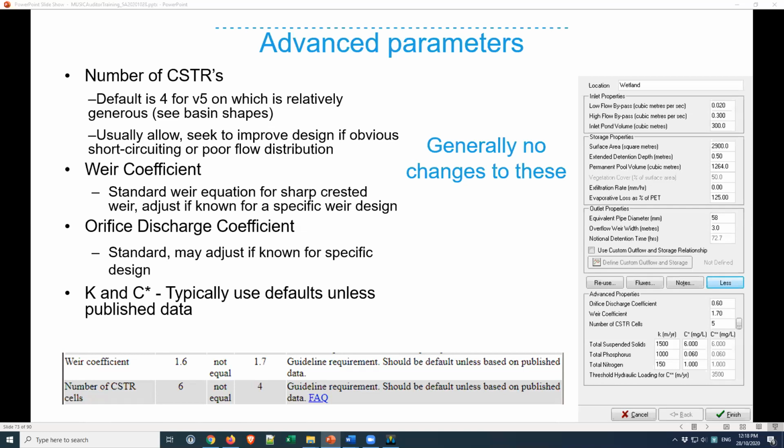Yep. So that's your permanent pool rather than your extended detention. It's worth keeping in mind that that's an average depth. So that doesn't stop you from having some deep pools in that wetland that are a metre deep or more, and then having some areas that are shallow. There's scope for more work to be done to look at that, what the ideal setup for that is. That could be made a little bit deeper if you think that that's needed to get through the dry periods.